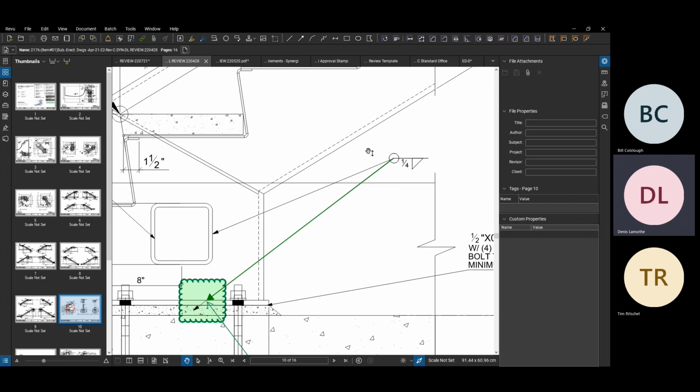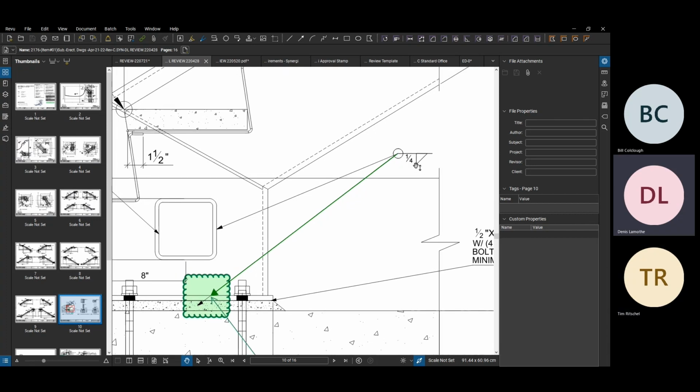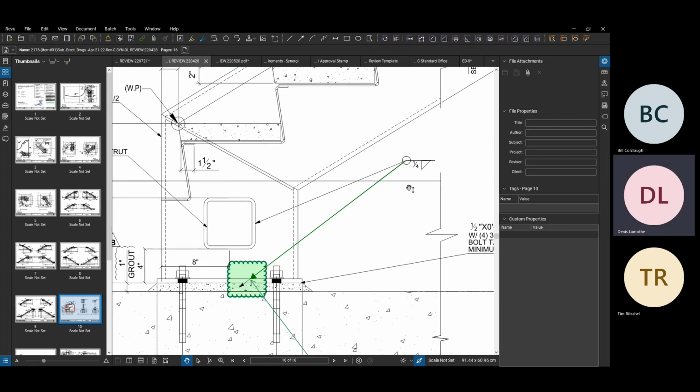Fillets and groove welds are the 2 main ones that we use. We have fusion welds, butt joints, or fusion or butt joint welds. We have plug welds, maybe a few others that we use here and there, or flared bevel welds. But the main ones are a fillet or a variation of a groove weld. So just making sure that we get the proper welds.